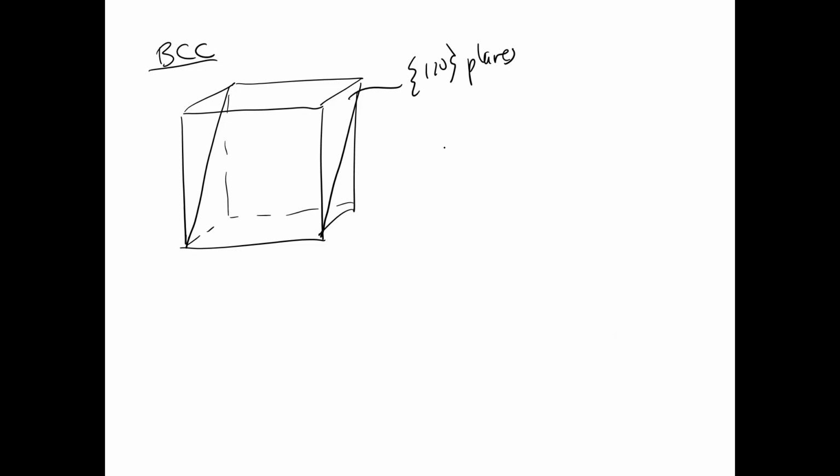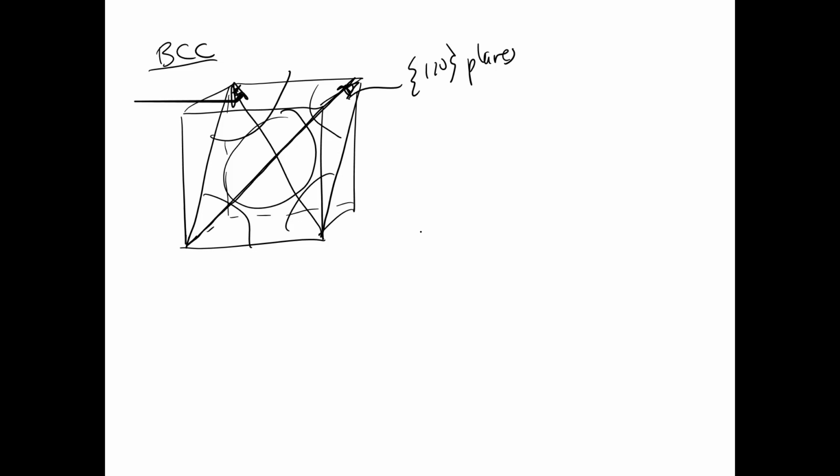And on that, if you were to draw where the atoms touch, they touch along here. So those two directions, they go all the way across, are two slip directions on that plane. So those are the 111, because they go all the way across the body diagonal, type directions. Now again, we could specifically label those. So that plane is actually the 101 plane that I've drawn, but it's in that family.